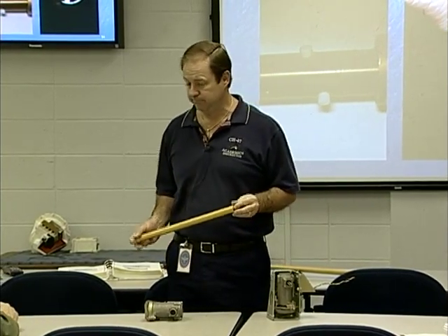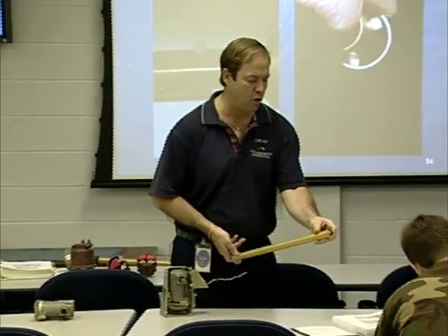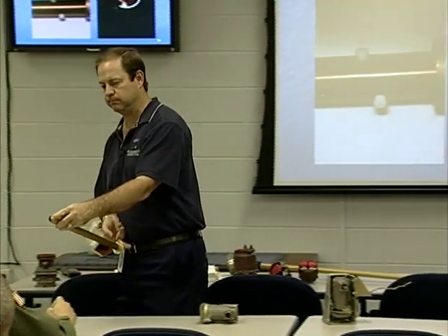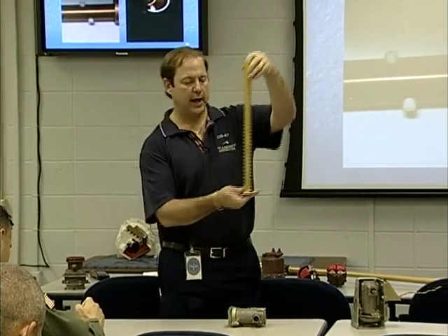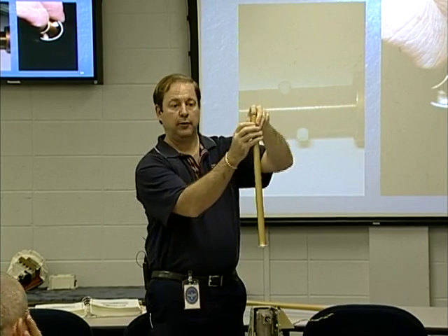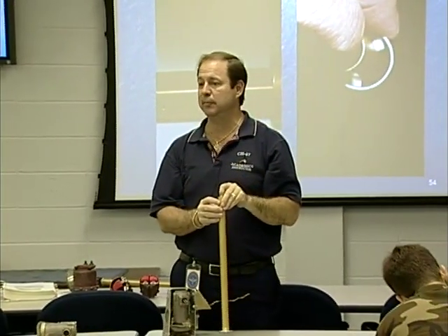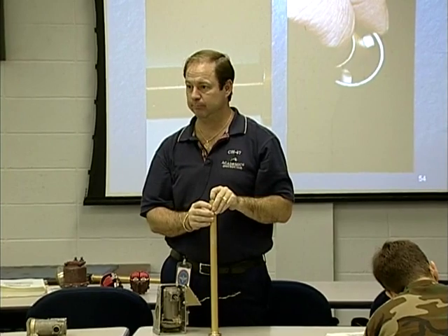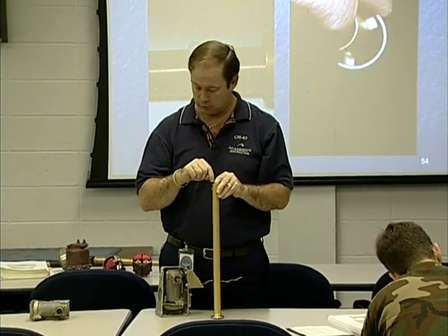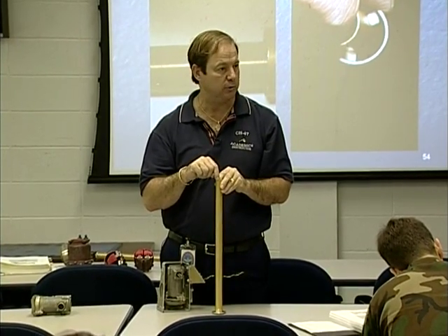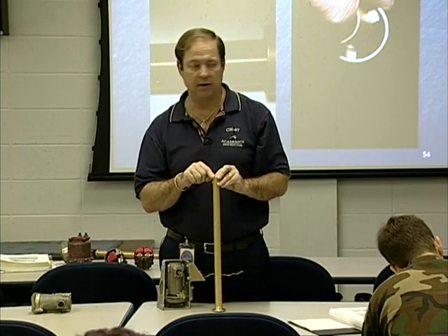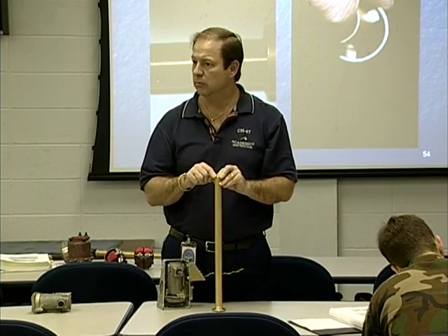Fair enough? Good. Now, what's going to happen is a small, minute amount of voltage is going to travel down that inner tube. So fuel is going to be able to come in between these 2 tubes, and fuel is a conductive medium. Meaning now it's going to allow power or electricity to transfer from that inner tube to that outer tube, just kind of using a variable resistance signal.